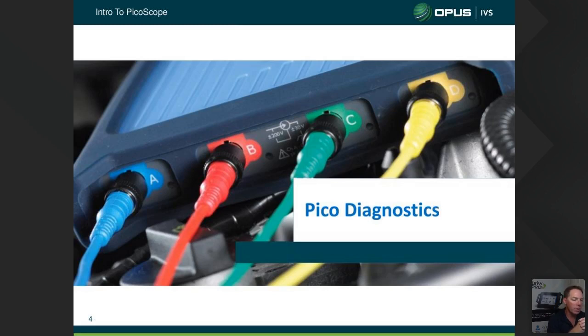And these are the tests that sort of replace what we used to do 20 years ago. I remember my boss used to tell me to check the basics first. A car came in for a tune-up or it was running bad: check the battery, make sure the battery's not flat, check the compression, before we start replacing plugs, leads, coils, anything like that. Do the basics, make sure that the exhaust isn't blocked, make sure that the air tract isn't blocked, there's no plastic bags clogging the intake. So they're the basic things that my boss used to tell me to do.